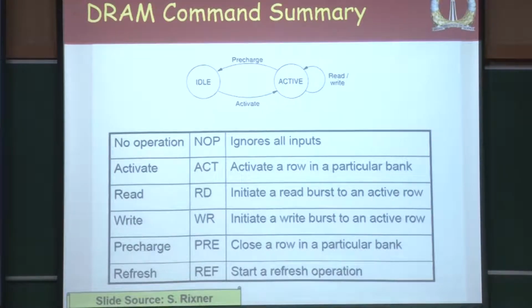That is called pre-charge, and as far as this row is concerned, it is idle, there is nothing else in the row buffer now. So, the new row has to be brought in, again with one more activate, and of course, you can again do the actions. That is essentially what it is. So, activate, pre-charge, and there are these reads and writes, which we call column access.